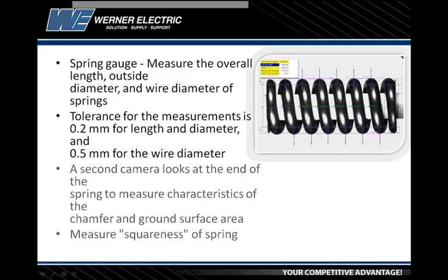If you look at the left side of the spring and the right, you can see that they're ground off flat, and that's a secondary operation. So that's probably being checked over closer to where that operation is. As I already mentioned, that's kind of best practices, is put the inspection right after the area where the operation is done so that you can have minimal scrap between the machining or manufacturing operation and the reject.